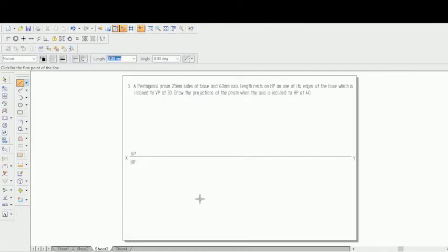Not to worry. You can just directly go and first draw a line like this, and just leave your mouse. Just enter the length and the angles. So just enter 25 as the side length, tab 0, enter 25, tab 72, enter 25, tab 144, enter 25, tab 216, enter 25, tab 288, enter. So now we have got the complete polygon.